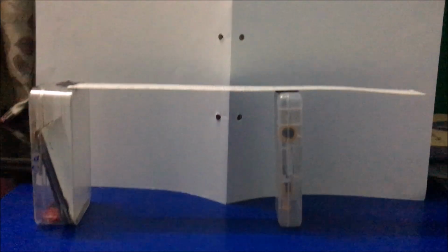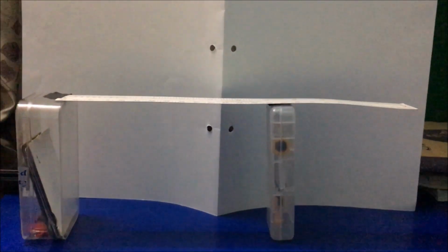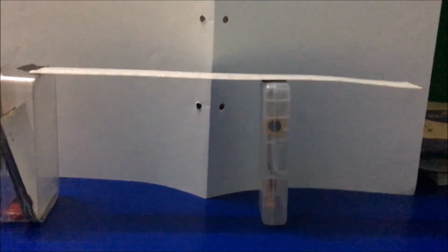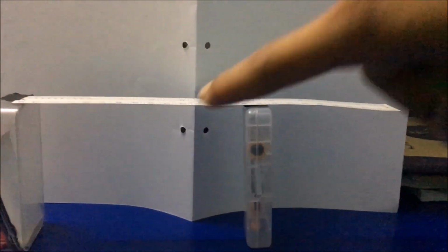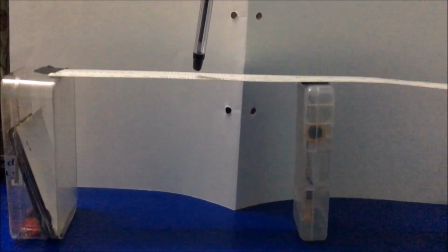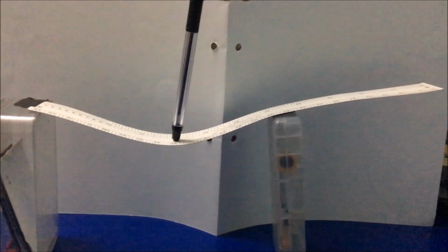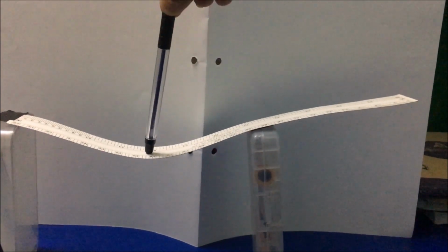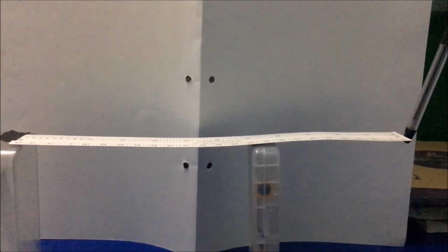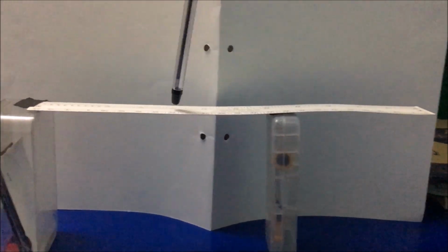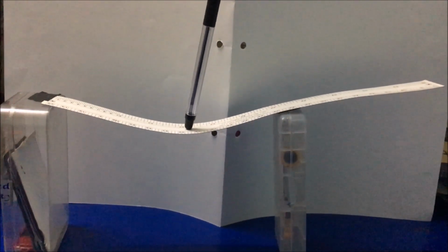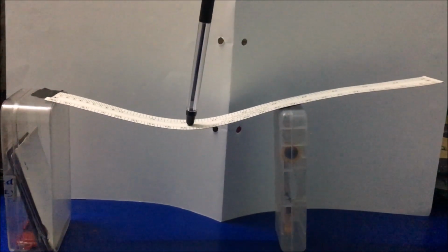As I have said, to illustrate, the very first condition is that the point load is acting at the mid span of the simply supported beam. If we see here on application, the deflected shape is maximum at the point load application, and you have to note this point. As we have plotted, it goes upward from the original point. So this is the first deflected shape.